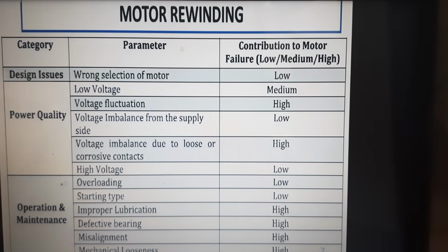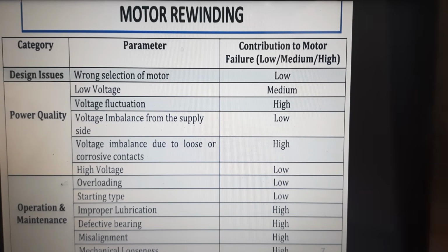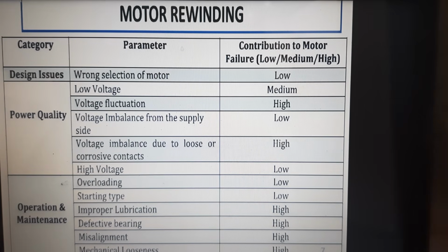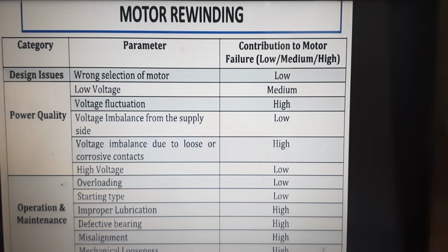Coming to the motors, there are contributions to, I don't say motor failure, but the motor being put to strain. It can be low, medium or high. The low ones we are definitely taking care of and attending to. But in the case of medium or high, there is power quality, like voltage fluctuations or voltage imbalance due to corrosive contacts at the incoming of the motor from the SSB to the motors.